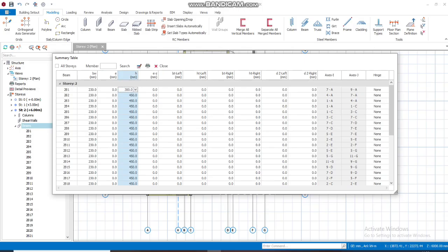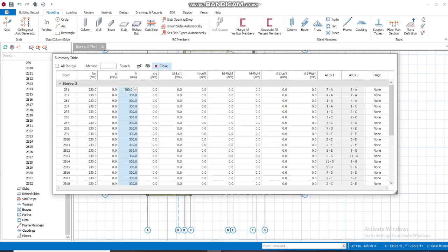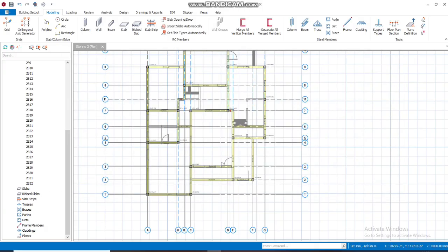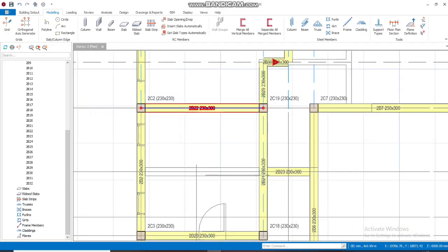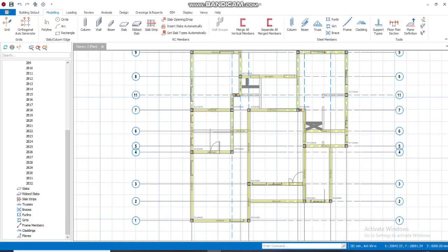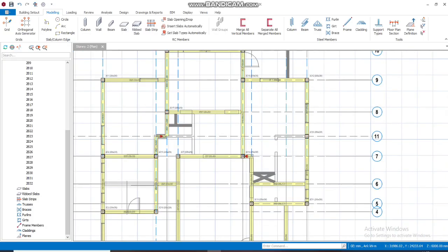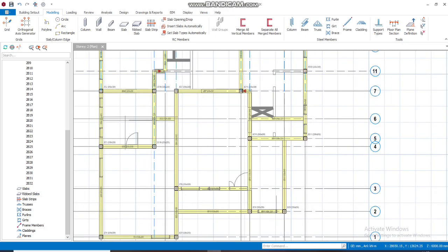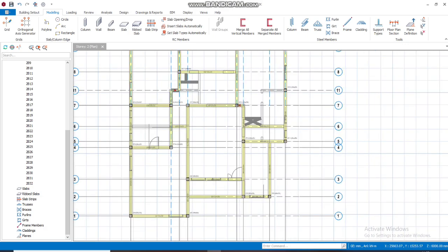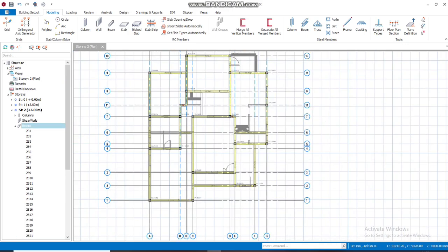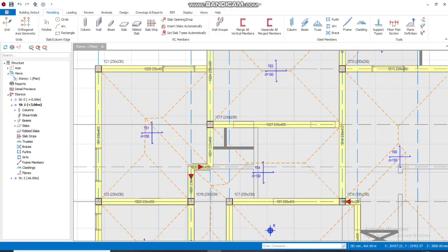So now back to our story two. The thickness of roof beams is 300, except where you have cantilevered beams carrying roof load. So we have to change the beams thickness to 300 because you generated it from the first floor, right? So we change it there.